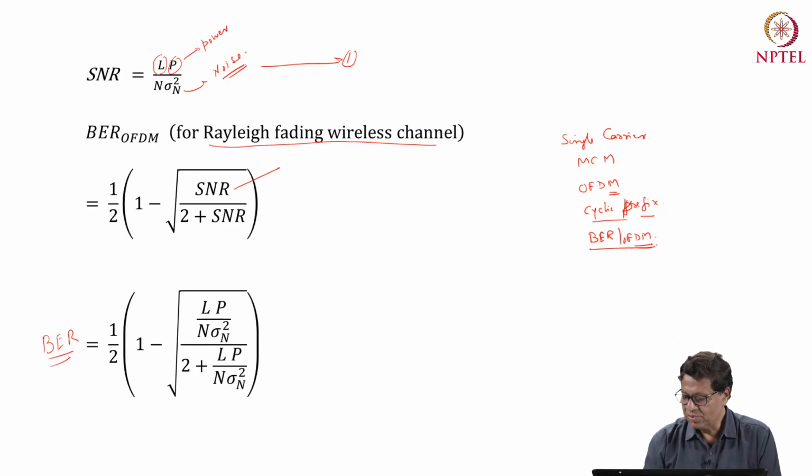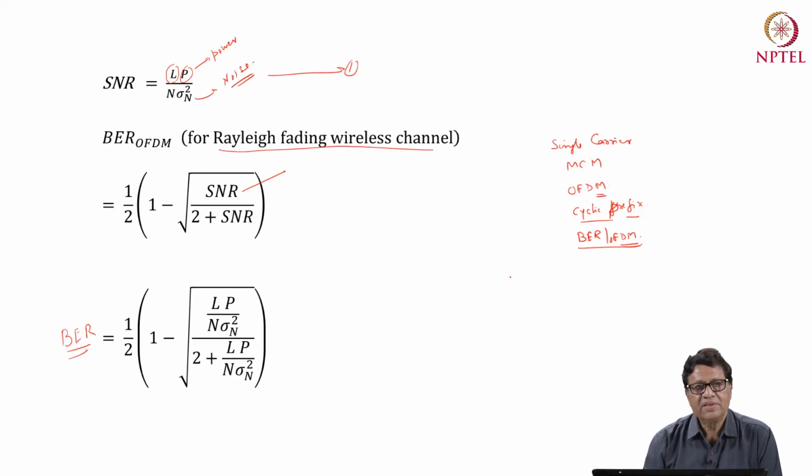So next what we want to study is the different subcarriers. It is possible that when the subcarriers are transmitted, there may be a shift. Suppose F1 was transmitted, and during the transmission there may be some shift, F1 plus epsilon or F1 minus epsilon. So we want to study the effect of this epsilon. I mean, how does it change the orthogonality of the system, and how does it change the performance of the system? This is what we will do in the next class,